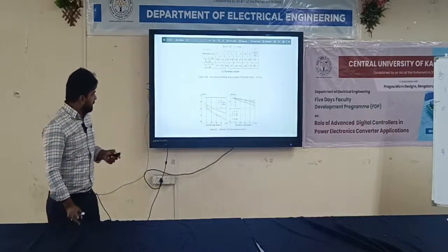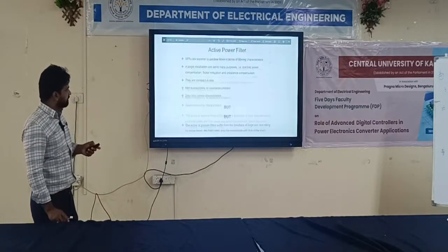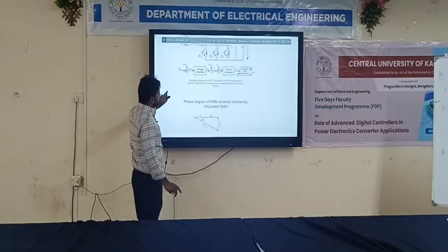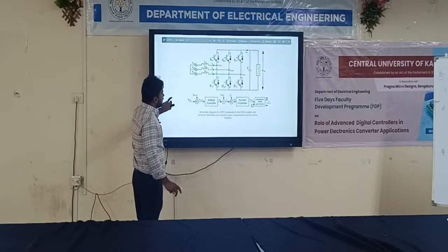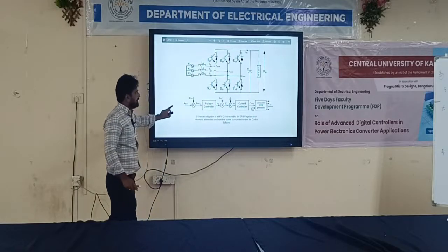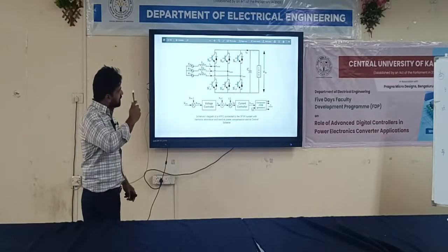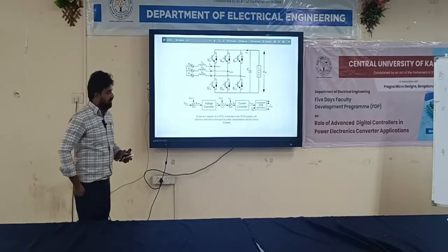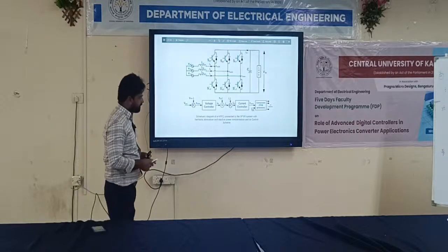So basically, using a high power factor converter with a control scheme, you could achieve a rectifier wherein you can control both the DC output voltage and also the source current. So let us take this concept.